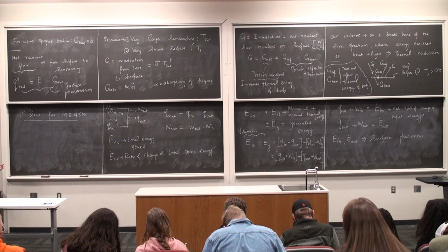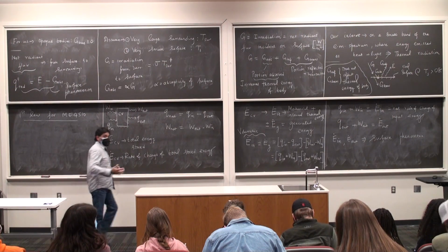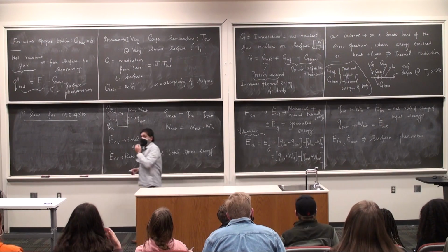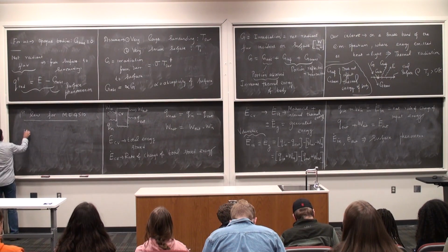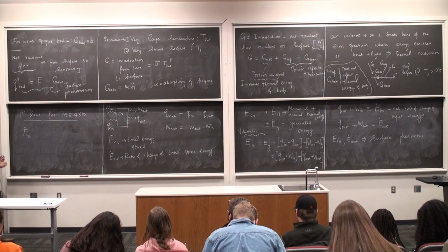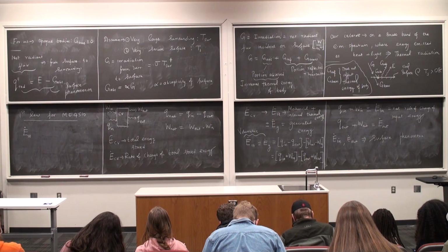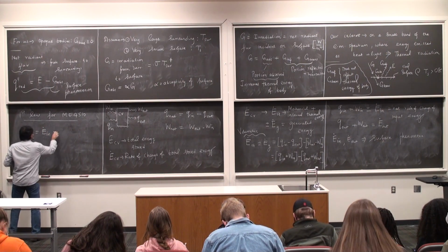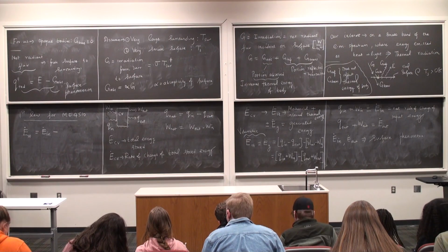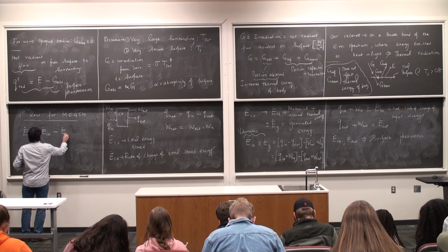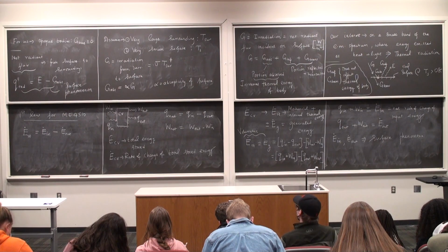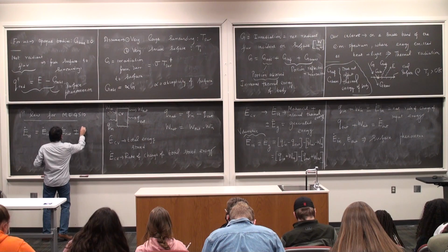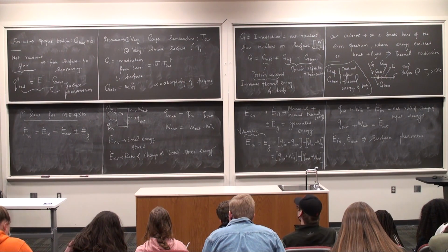And so if I combine everything together, and I'm going to do one more thing, I'm going to take this plus or minus E dot g and bring it to the right hand side, I end up getting the following equation. E dot stored, rate of change of the stored thermal and mechanical energy, is E dot in, which is Q in plus W in, minus E dot out, Q out plus W out, plus or minus E dot generated.